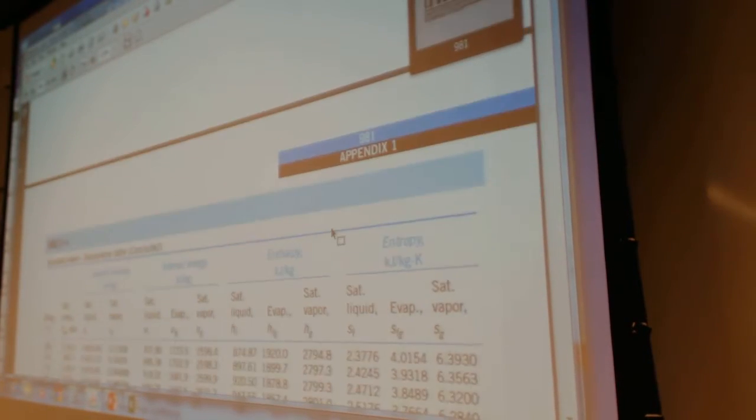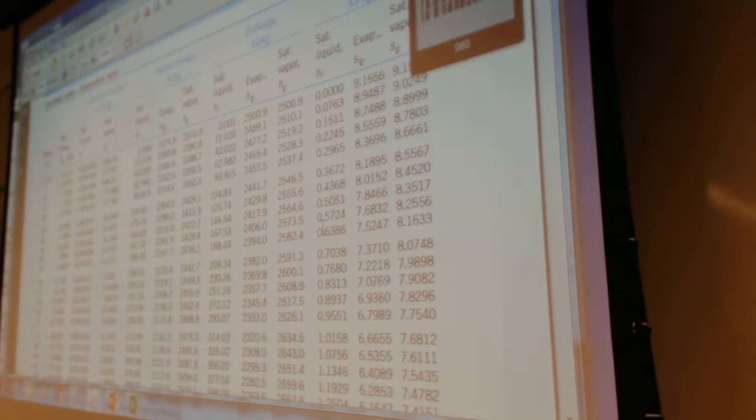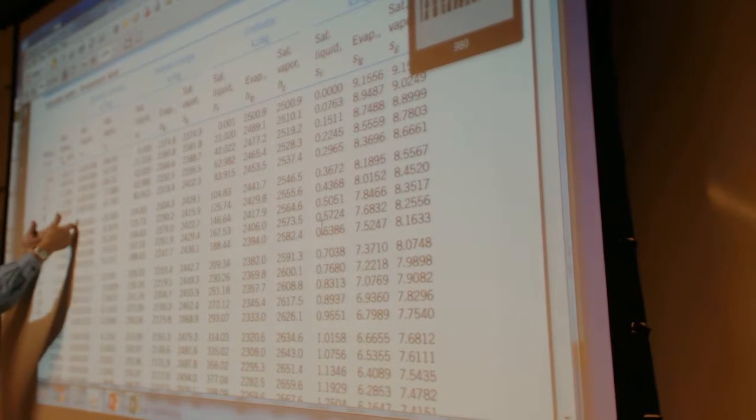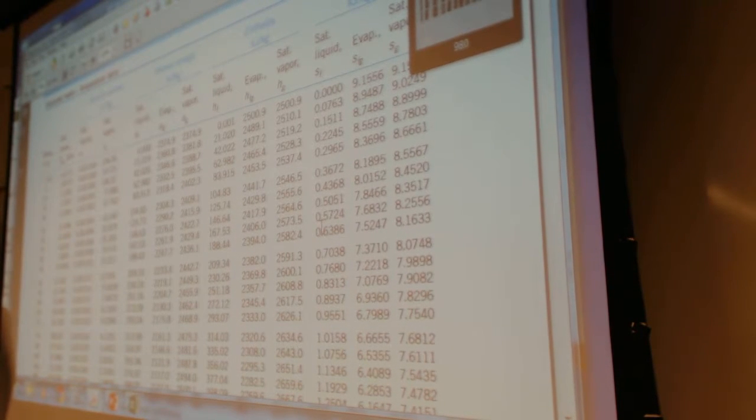Oops, too high. So according to this, what do we have for a saturation pressure? Oops, that's the pressure table, what temperature table? What we know is 25 degrees C. So if water vapor was all the way up to 3.1698 kilopascals, which would be 3% of the total, then it would be 100% relative humidity.